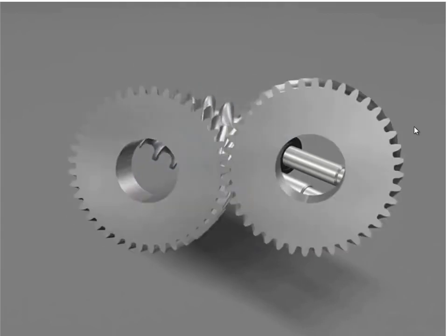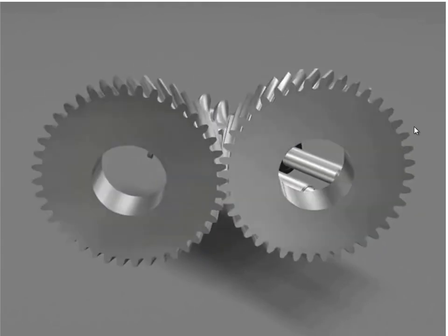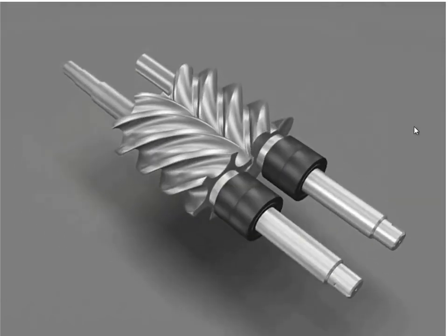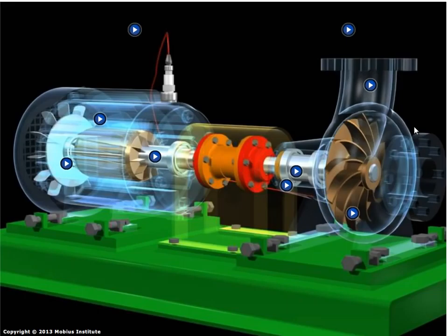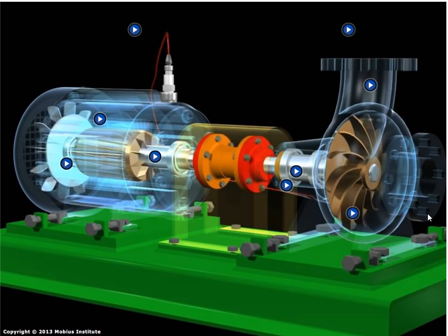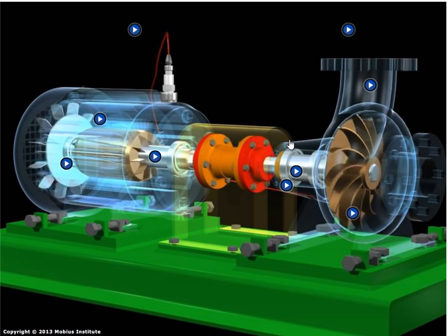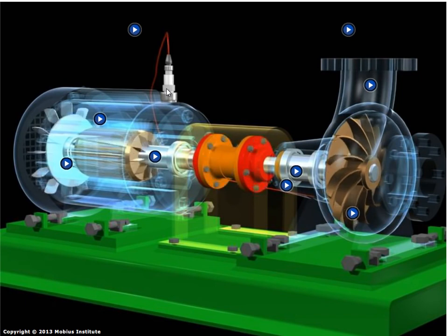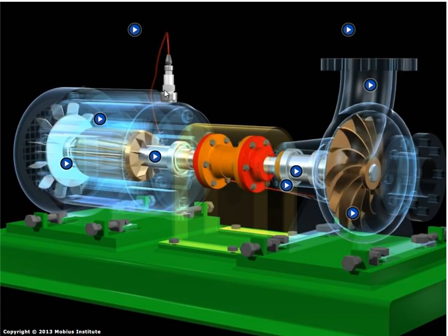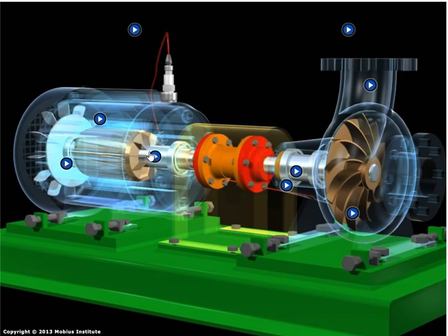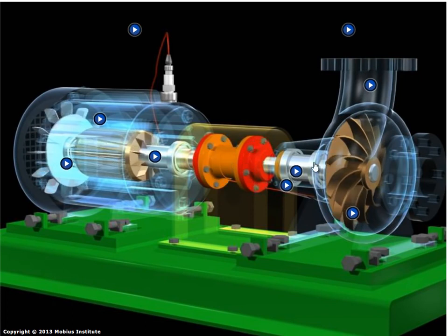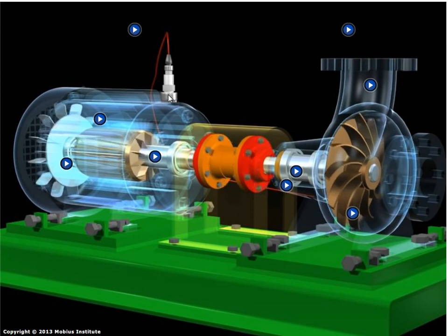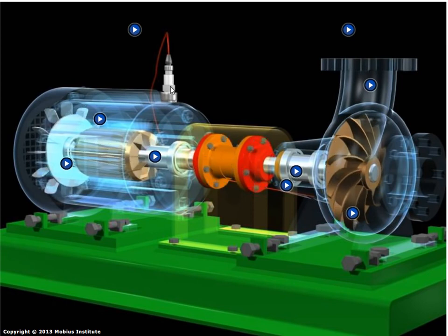Same goes with gears, whether they're timing gears or inside a gearbox. Are they aligned? Are they lubricated? Is there damage to the teeth? Anywhere? Whatever the case may be. Vibration analysis lets us look inside the machine. Now, in this case, we've got the motor driving a pump and a vibration sensor sitting up on top. I'll explain a bit more about that in just a moment. But you may first imagine that all the vibration is transmitted along and goes up to this point, and maybe from this side as well. And that's one of the things I'll mention a bit more about in a moment. Just where is the vibration coming from and how's it getting to that sensor?